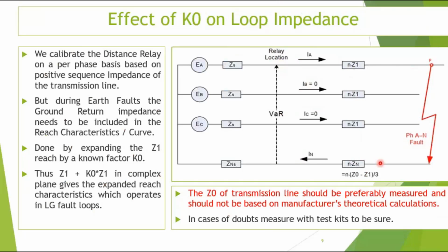And this is the equivalent of the return path of the earth fault current. Now, the return path of the earth fault current consists of the ground wires, maybe the ground itself. We don't really know the impedance of this portion. We are in the dark about this one. The return path impedance we don't know. So how are you going to catch this fault? And how are you going to be sure that the distance to this fault, or the impedance to this fault, is calculated properly without knowing the return path impedance? Therein this mathematical logic of sequence components comes in.